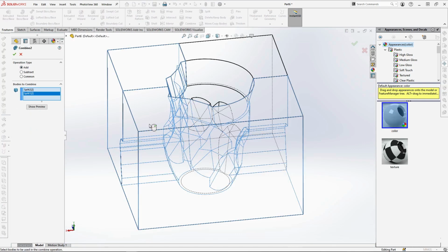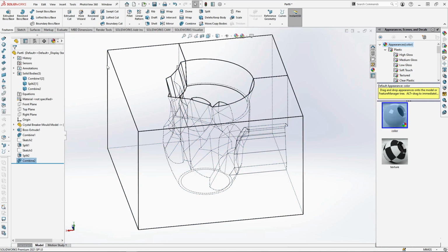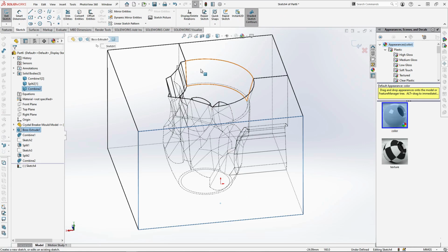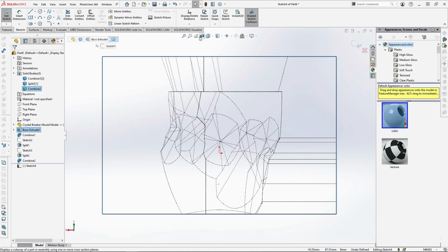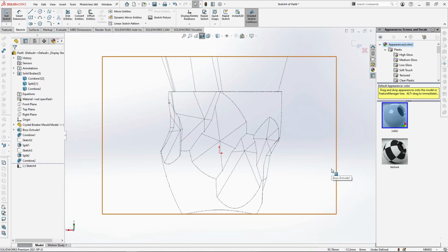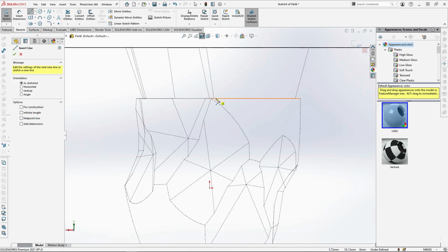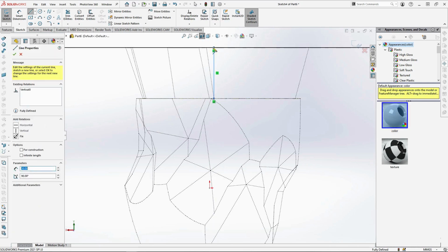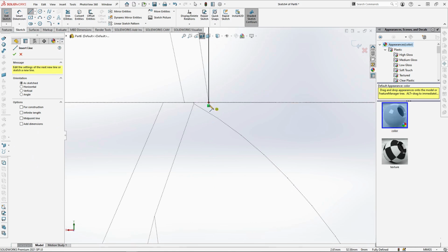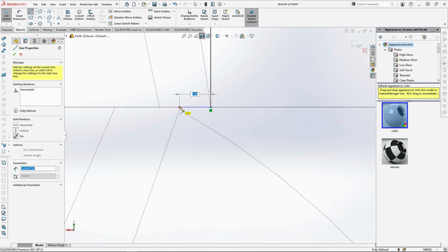We still have the two split lines we created, and we can now create the third. Sketching onto this face, turn on section view. With the line, sketch up from this point to the mould edge. Then another small line along the top edge here to this point.